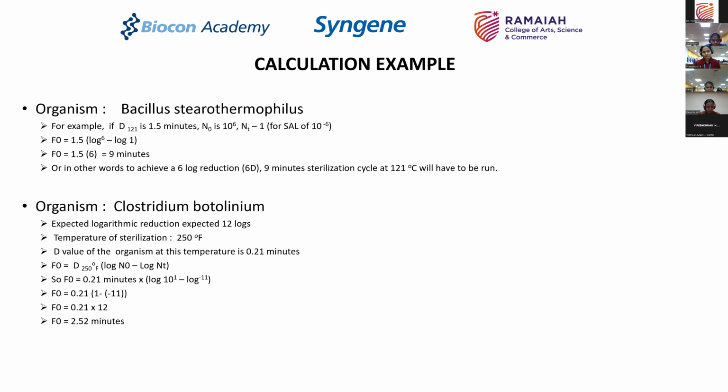So why is this important in the food industry? Because in the food industry, you don't have the luxury of batch autoclaving. In a sterile manufacturing facility, you can do the autoclaving under batch operation, meaning that you load the autoclave, finish your autoclaving cycle, unload it on the other side, prepare the second load, load it after that, and run maybe 5 or 6 loads in a day.